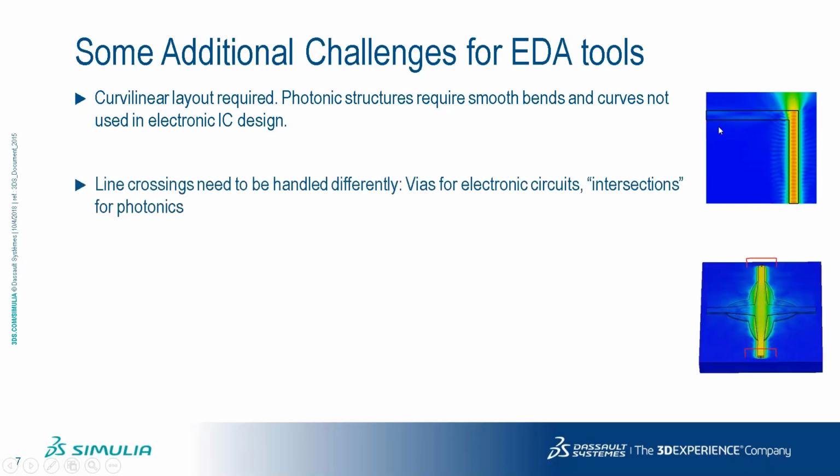On the other hand, you also don't have to worry about shorts so much. Obviously, if you do electronics design and you have 2 wires touching, they're automatically shorted, and you can't do that. So that's why when you do PCB design, you typically have a via going to a different layer, and then it's routed underneath, and then it comes back to this layer through another via.